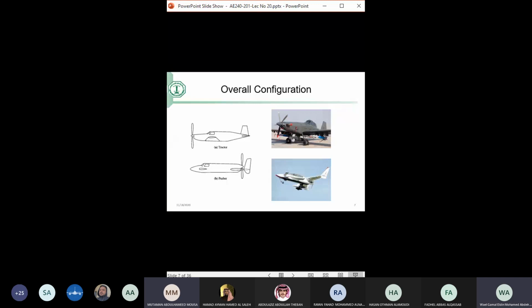So you are comparing between the pilot and the engine, but also there is the wing, right? And there is the tail, there is the structure, there is the landing gear. So let's put it this way. If you put the engine in the back, that will move the CG aft, right? The CG will be a little bit behind. If you put it in front, the CG will be a little bit forward because of all the components. So we are comparing whether we want the CG forward or we want the CG aft. Now, from this point of view, the forward position would be better.